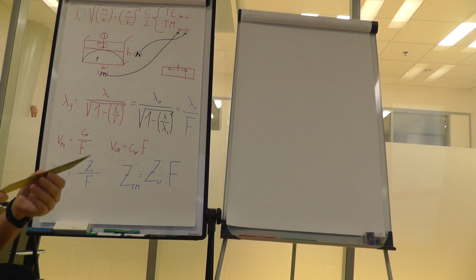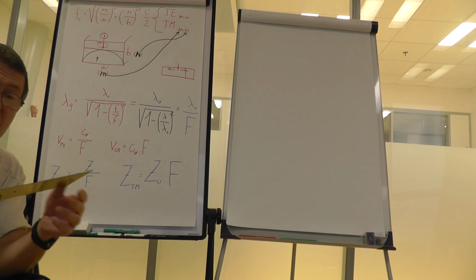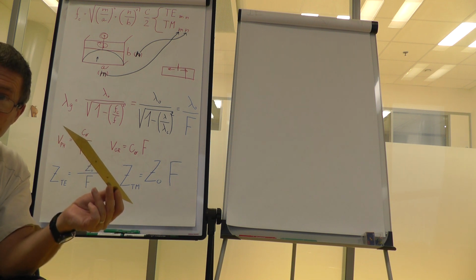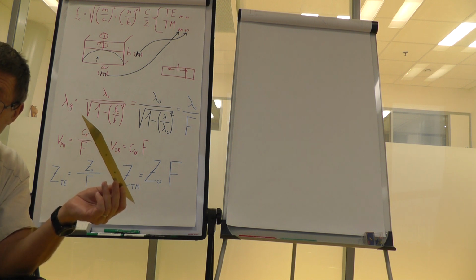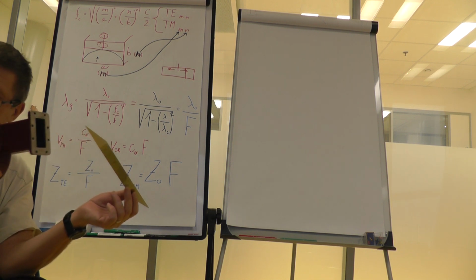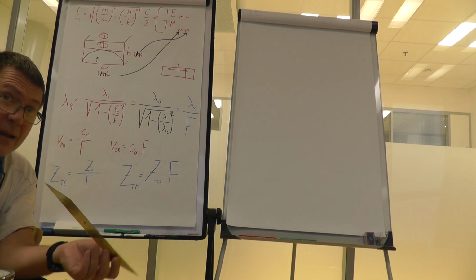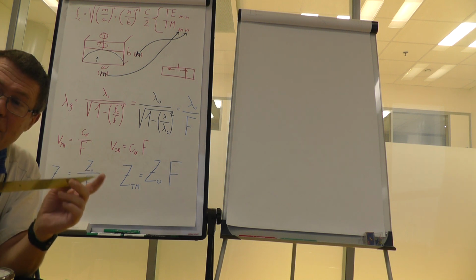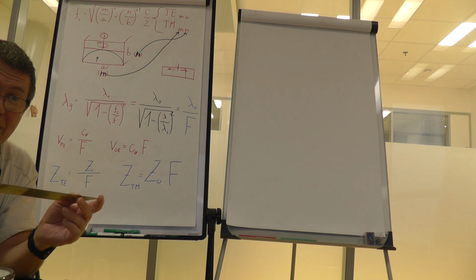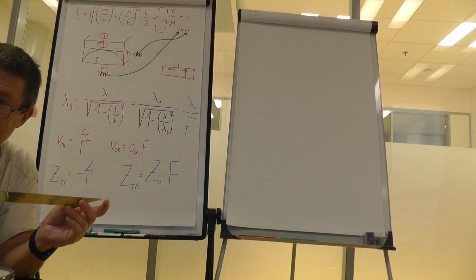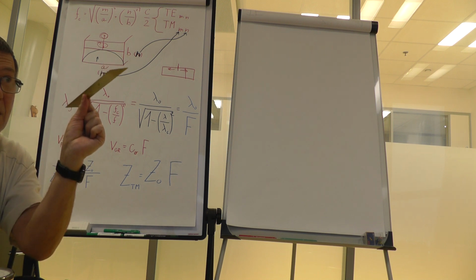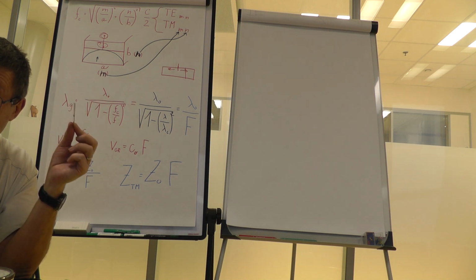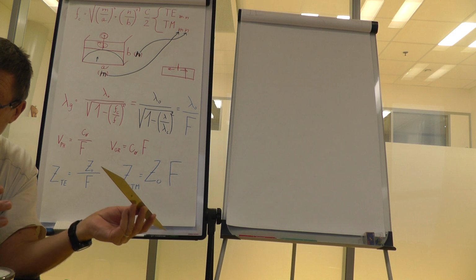Now I have shown one possible use. We put this into the waveguide to change the magnitude of the wave propagating, to have a variable attenuation. So this is called a variable attenuator then. In some other cases, we just want to keep the magnitude intact, but what we need to change is the phase of the propagating signal. And now again, we just take another insert which is not lossy, but is a piece of non-lossy dielectric.